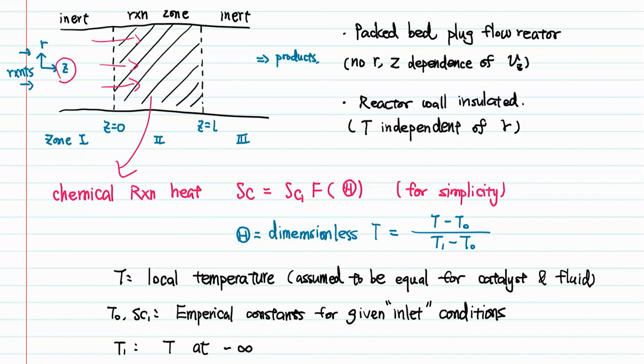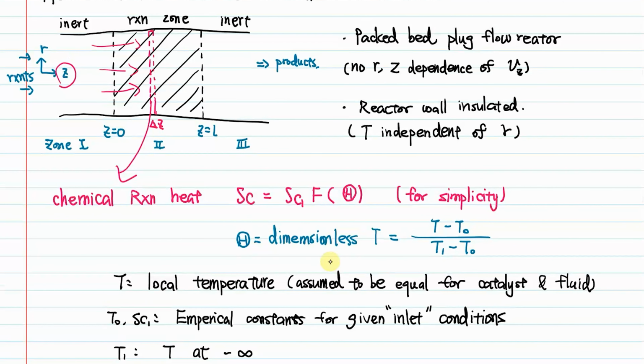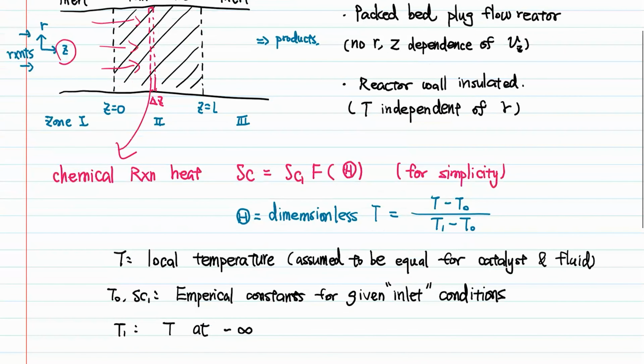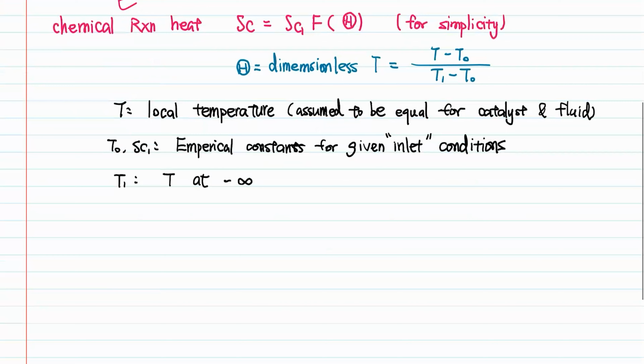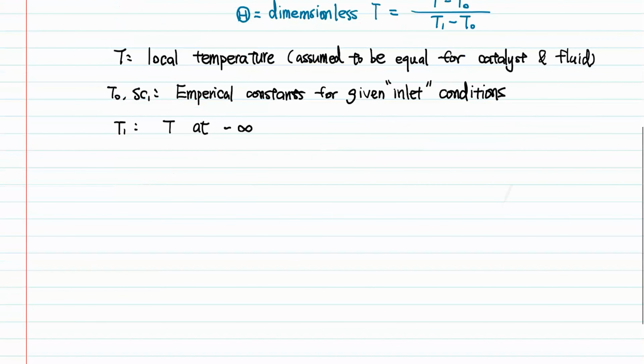So if I were to guess how the shell should be defined, I would guess that it should be a very thin shell in the delta z, or in the z direction. That's because that's the direction where the temperature is changing and the direction of energy transfer or transport. With the shell determined, we can now perform our shell energy balance.